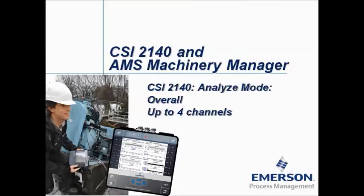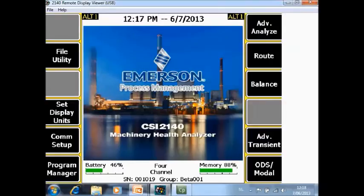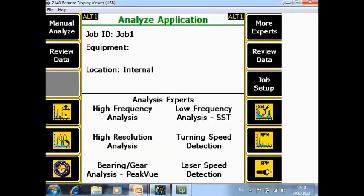This video tutorial explains how to collect, in the Analyze mode, overall values on up to 4 channels simultaneously with the CSI2140 Machinery Health Analyzer. This is the home screen of the CSI2140 Machinery Health Analyzer. To collect overall values, go to the Advanced Analyze with F7 and select here Manual Analyze